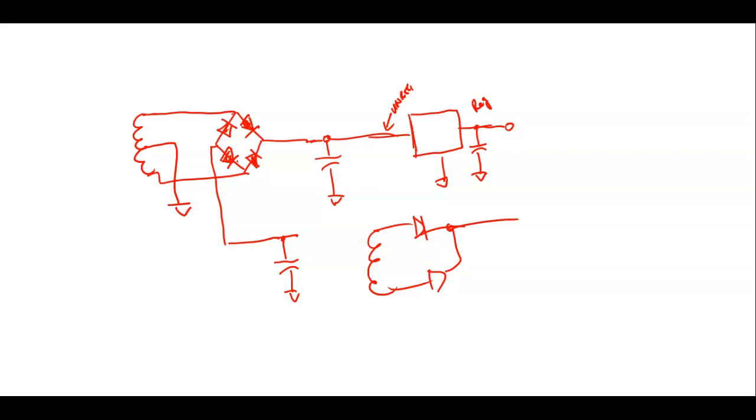We just did a regulator. We called it a Zener regulator. So even though my input a while ago was changing between 7 and 6 volts, my output load was changing between 2.5 milliamps and 7 milliamps. My output voltage stayed within 5.1 volts, 5%, right, the whole time. So it's regulating the voltage.